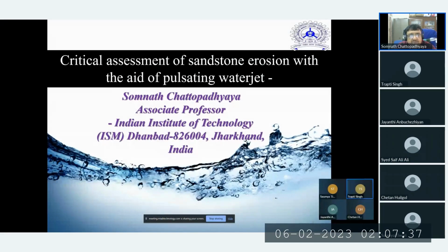There are some limitations with abrasive water jet. The problem is that we have to mix the abrasive in appropriate mixtures, and then there is the handling of those abrasives and the recycling of those abrasives. Those are the things that are there. It also cannot work at low pressure.